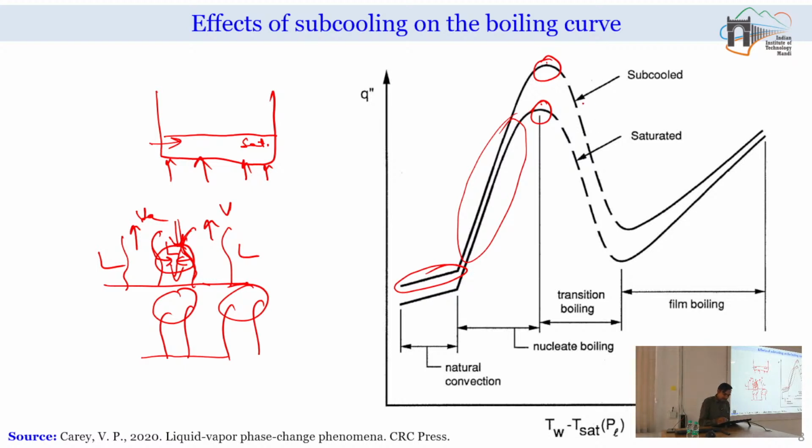And of course, this part is significantly dependent upon continuous re-wetting and non-wetting. So here it will be changing a lot, but again in the film boiling regime, once we enter, we will not experience much change because of subcooling of the pool.